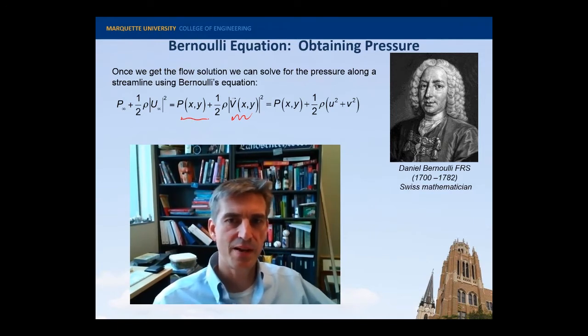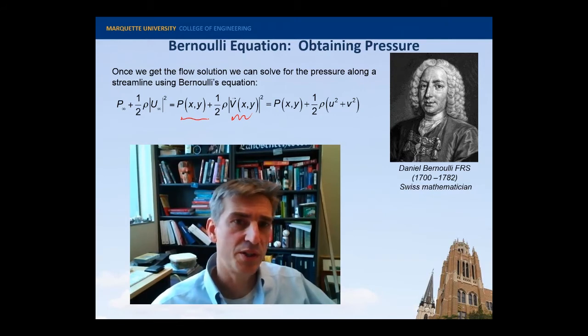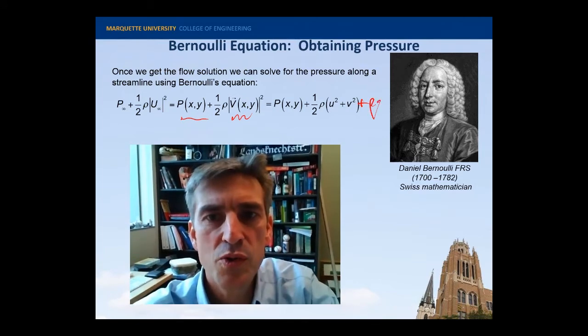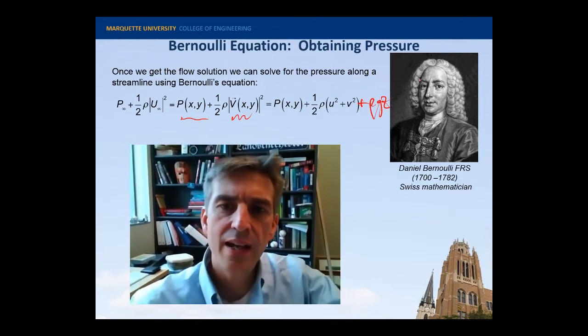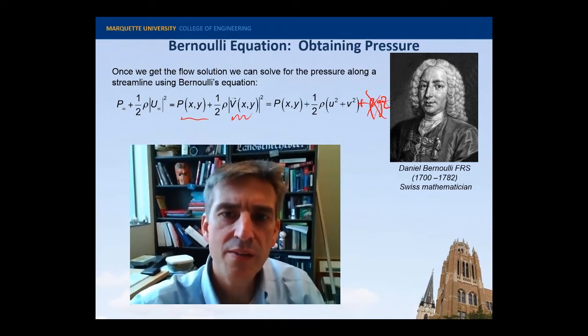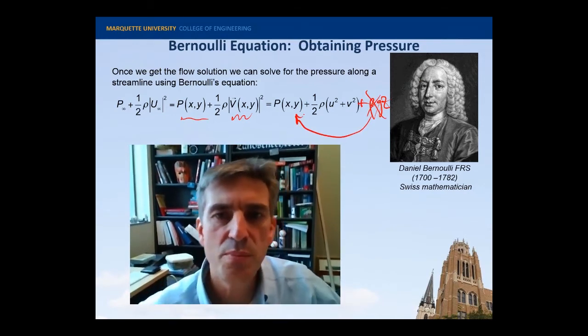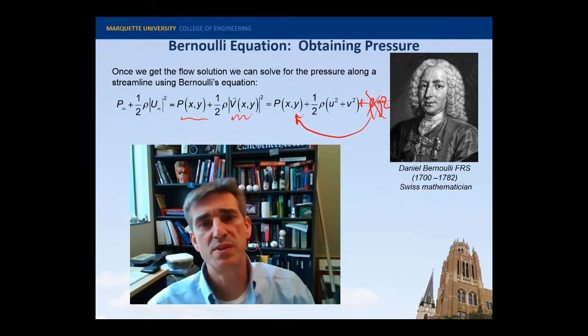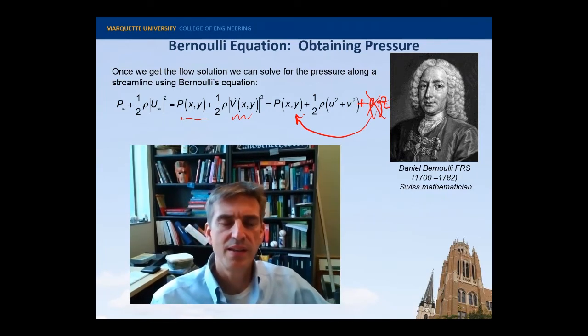A couple of things about this equation. I've written it without the hydrostatic pressure, right? Normally there's another term here, something like plus rho g z. I didn't write that term because we can think of it as being embedded into the pressure term. So the hydrostatic pressure together with the thermodynamic pressure is an easier way to write these equations.